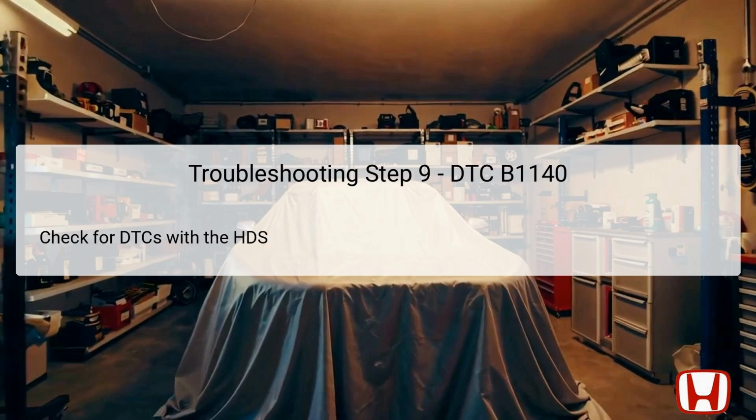The final troubleshooting step involves checking for DTCs again with the Honda diagnostic system post-manual operation of the power window. This is a decisive moment where you can evaluate the effectiveness of your previous steps. If DTC B1140 reappears, it leads to the conclusion that the driver's power window motor is likely faulty, making it necessary to replace the driver's door regulator, as that motor is integrated within that assembly.